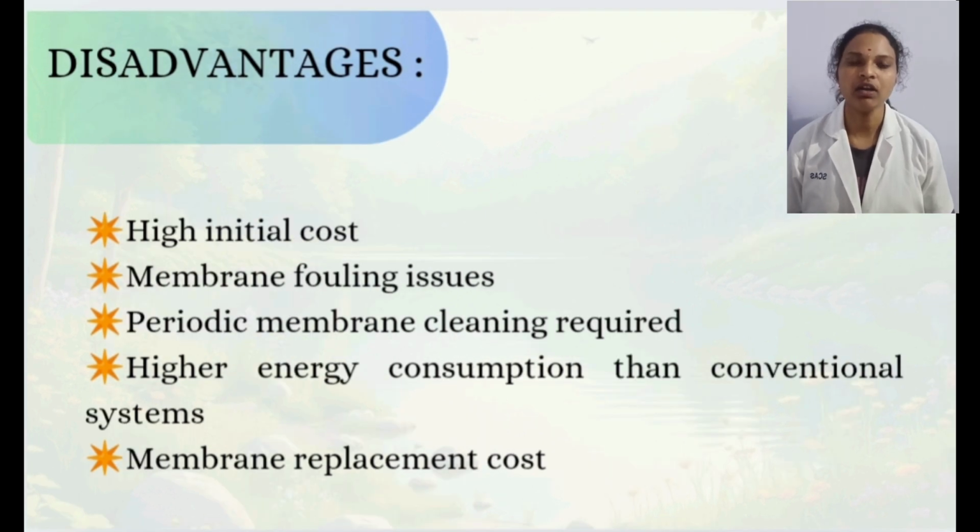Disadvantages of the MBR: the membrane bioreactor is expensive. It may cause some fouling issues in the membrane. After one cycle, a cleaning process is required for the membranes. It has higher energy consumption than conventional systems. The membrane replacement is also expensive.